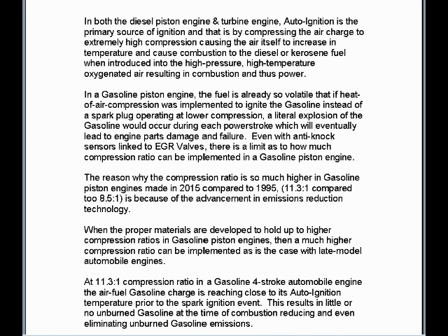In a gasoline piston engine, the fuel is already so volatile that if heat of air compression was implemented to ignite the gasoline instead of a spark plug operating at lower compression, a literal explosion of the gasoline would occur during each power stroke, which would eventually lead to engine parts damage and failure. Even with anti-knock sensors linked to EGR valves, there is a limit as to how much compression ratio can be implemented in a gasoline piston engine.